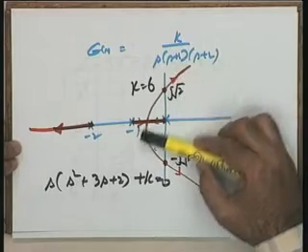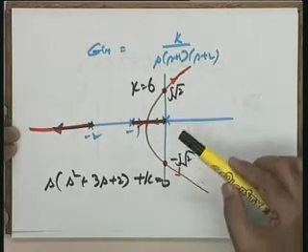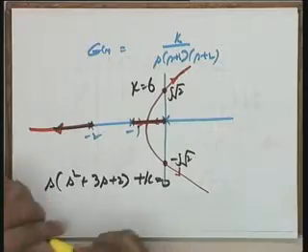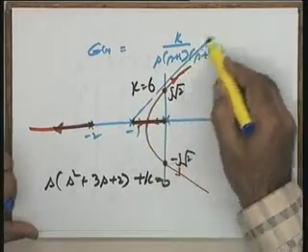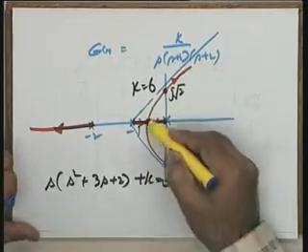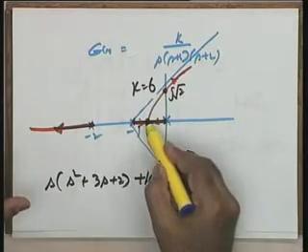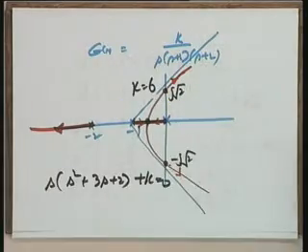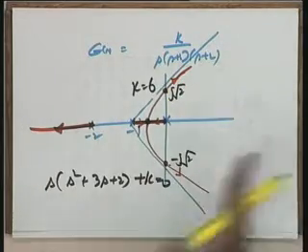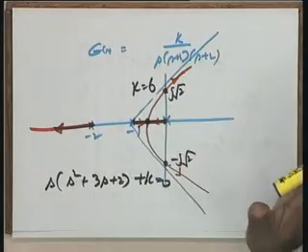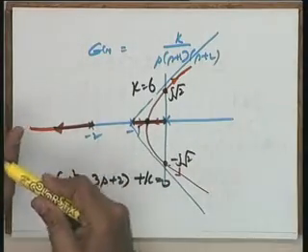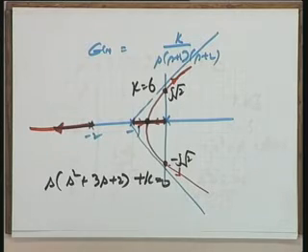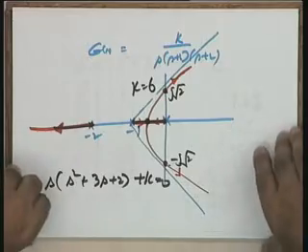It gives a method of sketching the root locus, a rough root locus, because what you had were the following. You had this, for example, these are the asymptotes, you know. This is the breakaway point you have calculated. So, this breakaway point, these asymptotes and these additional 2 points give you sufficient information to make a rough sketch of this system. This way, all the rules can be utilized to make a rough diagram, and from that rough diagram, the analysis and design can follow. Okay? This is the total quota of rules. And you do not have to remember these rules.